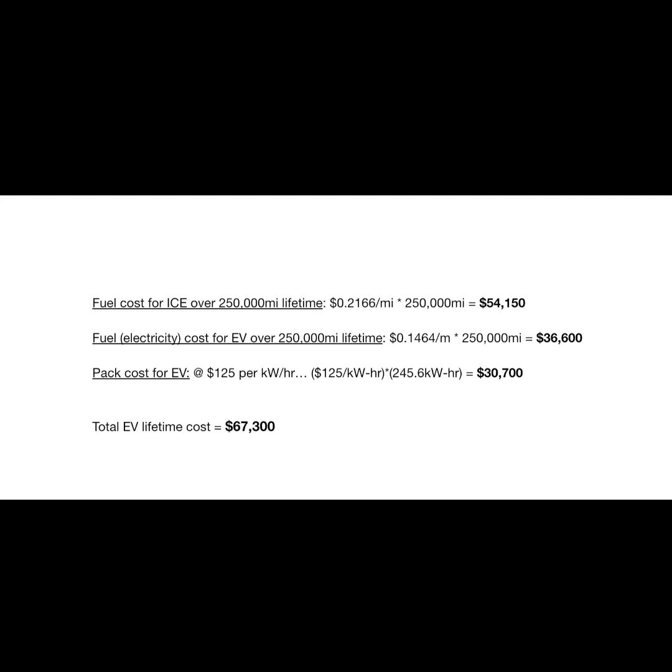However, in order to convert my truck to electric, I need to buy a battery pack, and at $125 per kilowatt hour for a lithium iron phosphate battery pack that has enough capacity for a range of 350 miles, I'd end up paying $30,700. This puts my total EV lifetime cost at $67,000. That's even more than the already egregious $54,000 that I would pay in fuel if I kept my powertrain stock. So to me, this swap is not worth it.